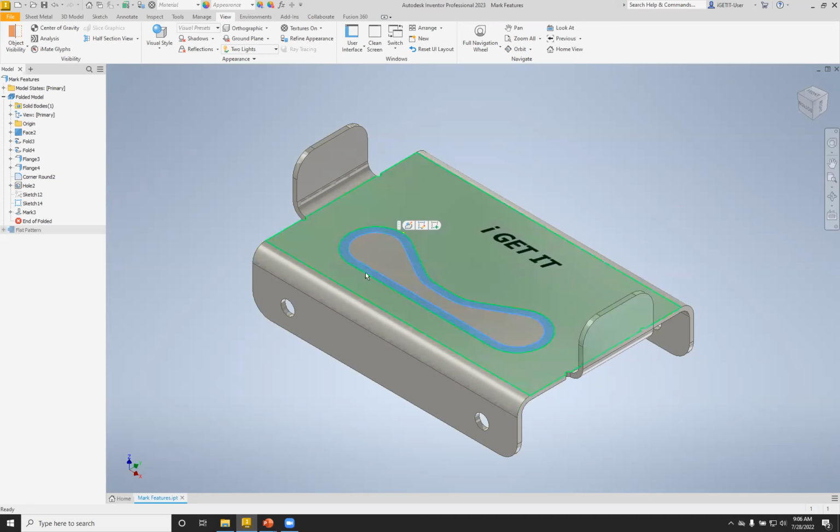Because this now is a separate face on this surface, we can use that, and we can add a different color to this. My menu comes up. So I think this is really, although it's kind of created so that you're going to use this for etchings or engravings, I actually see a lot of use for this. If you're creating different paint lines or different things that you want to represent on that surface and want to be able to change colors, this is a really quick and easy tool to do that.